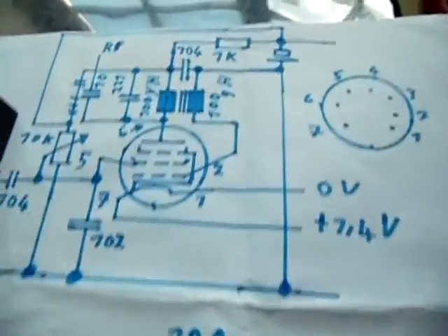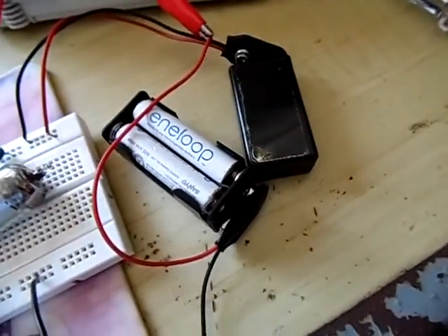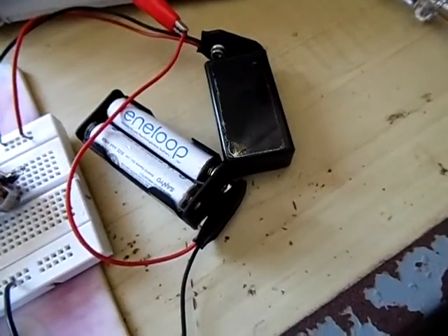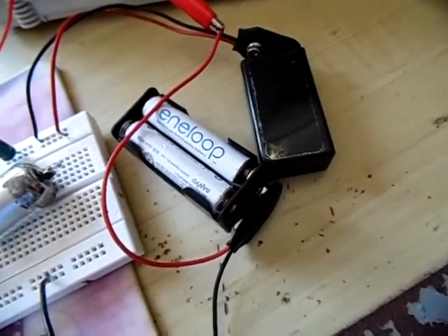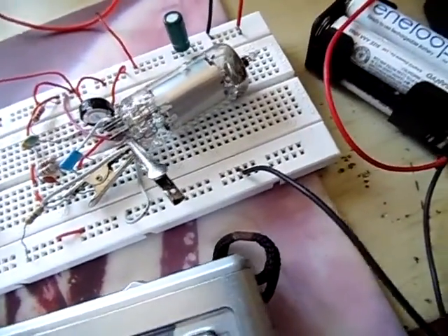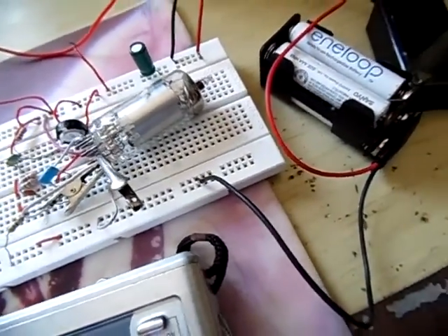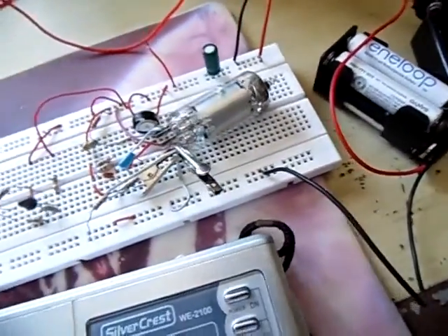So now let's talk about this transmitter. This is a Meissner oscillator transmitter, and the cool thing is that here you can see my supply. This is the heater supply, and this is the anode voltage. You may be wondering, why is there a 9-volt battery when I'm talking about anode voltage? Well, it's something special about these so-called battery tubes. They will also work with a very low voltage, in this case just from a 9-volt battery.